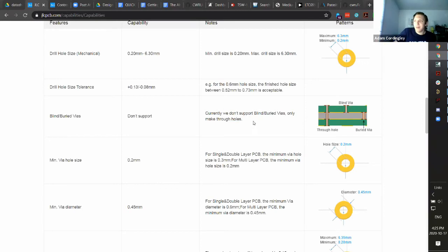So it doesn't matter anyway if we're getting our boards from JLC. But they're also more expensive. With any manufacturer that you get your boards from, the price could go up by 10 times when you ask for blind or buried vias. If you need them, you really need them. But on 95% of designs you will ever do, you do not need blind or buried vias.